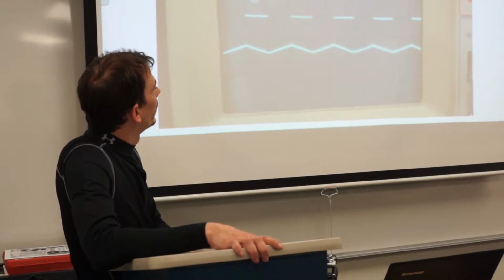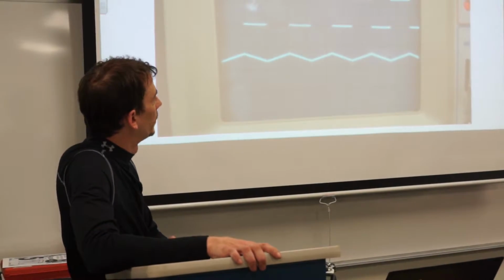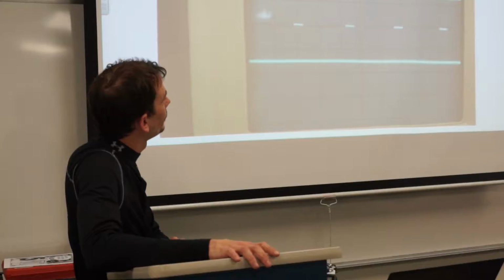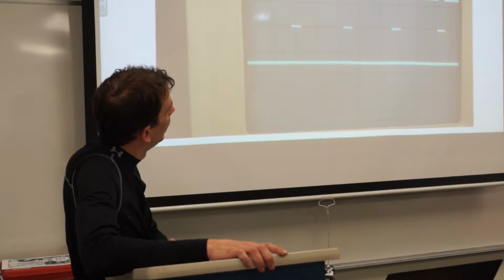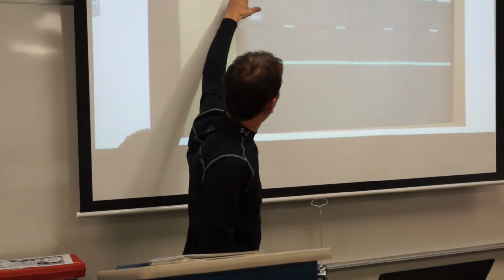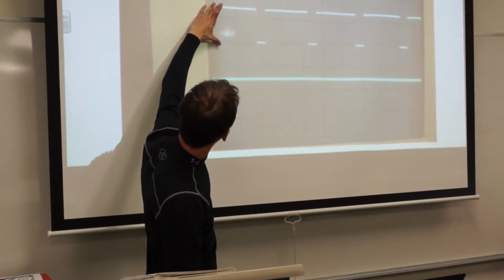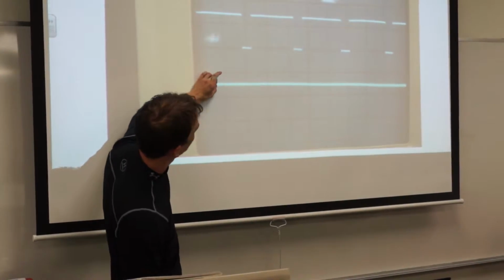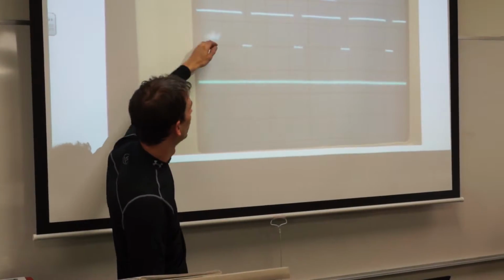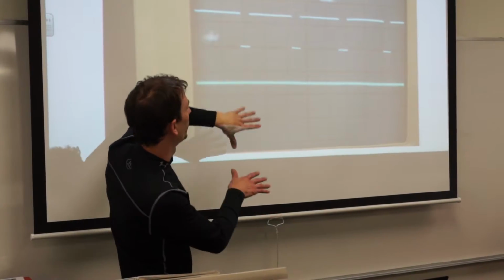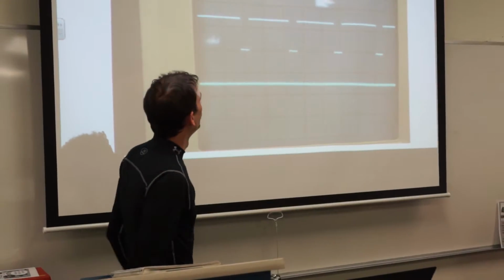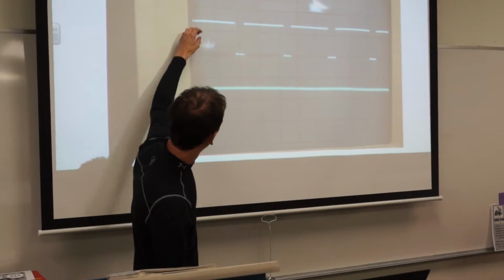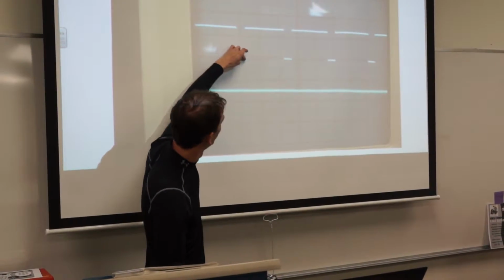I think, yes, these are all final version output shots here. That shot there is at almost max power. This is 2 channels on our oscilloscope. This is the output from the comparators we're looking at, and this is the DC output that we're shown. They're not using the same 0 lines, they're separated, but just for a scale of noise of what we're seeing, here's our high pulse, here's our low pulse, a short duration low.